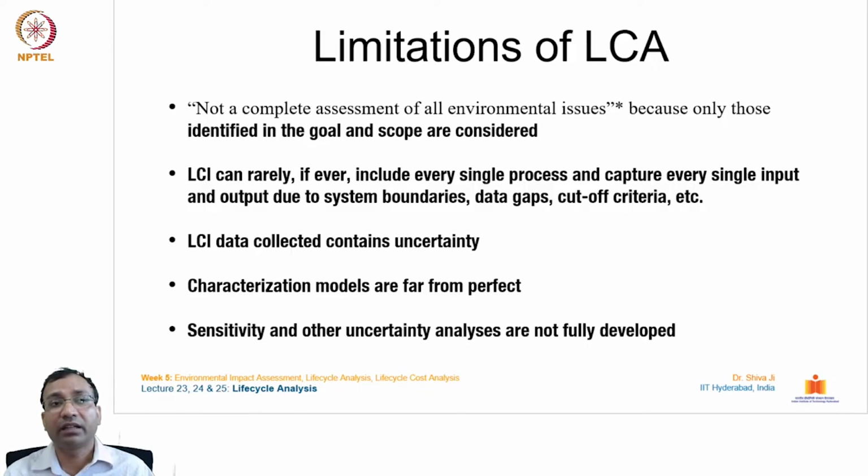LCA can rarely, if ever, include every single process and capture every single input and output, due to system boundaries, data gaps and cutoff criteria. So there could be some limitations while undertaking the study itself: whether the system boundary is defined, whether all of the data is available, whether the data is available in a quantifiable format, because LCA analyzes only quantifiable formats. So if there is some data which is subjective in nature, that cannot be processed under LCA.